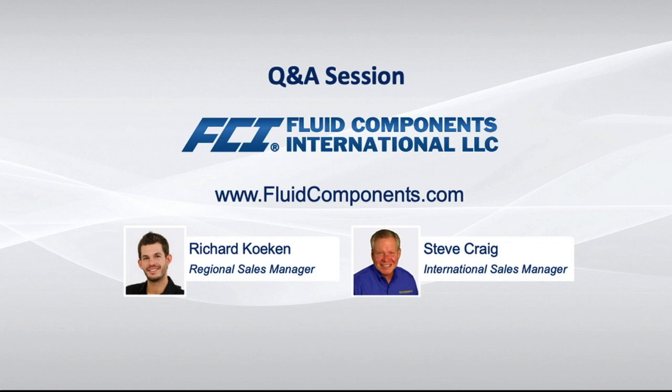This person is asking, you were showing multiple measuring points. How many points can be supplied with one flow measuring system? Thank you, Katie. Yes, we have shown during the presentation the number of measuring points are depending on the application accuracy requirements. More points do not always necessarily mean additional accuracy. There is an optimum number of points required for the specific pipe size.